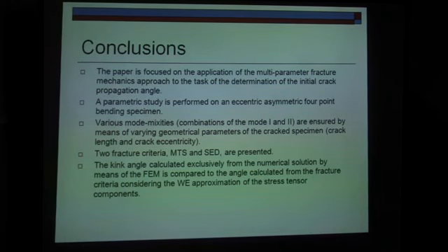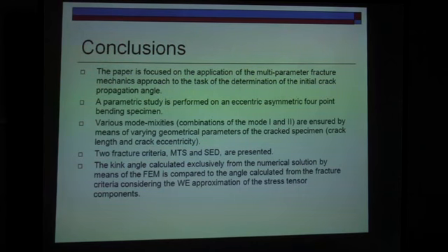Let me conclude. Our paper is focused on the application of the multi-parameter fracture mechanics approach to the task of the determination of the initial crack propagation. The parametric study is performed on eccentrically asymmetric 4-point bending specimens, and we use for this evaluation two fracture criteria: maximum tangential stress and strain energy density, and we calculated the initiation angle for crack propagation.